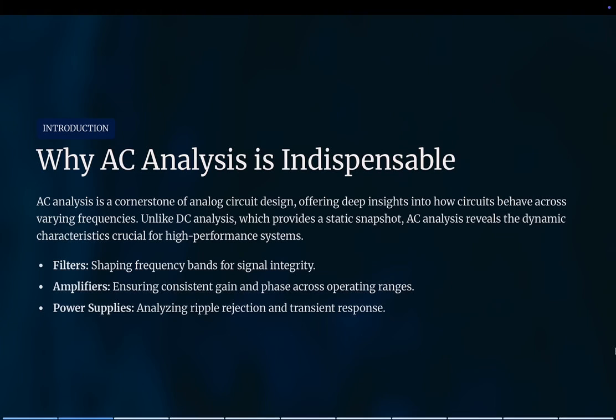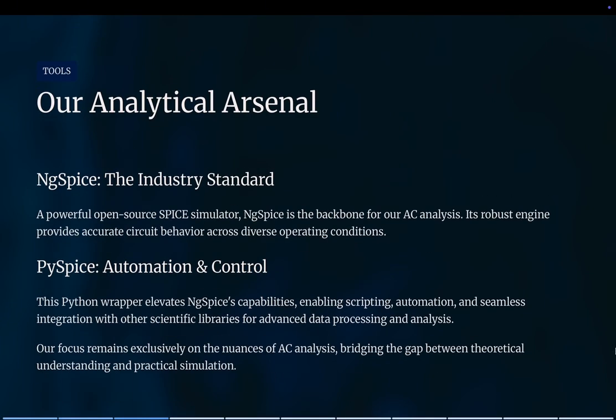With AC analysis, we can see the frequency response of the circuit, draw Bode plots that show how the circuit behaves, examine the phase of the output signal relative to the input, and in circuits with feedback, check the stability of the system. To do this work, I used Ngspice. Ngspice is an open source and free simulator built based on classic Spice. This tool is widely used in industry and has the same power as commercial simulators.